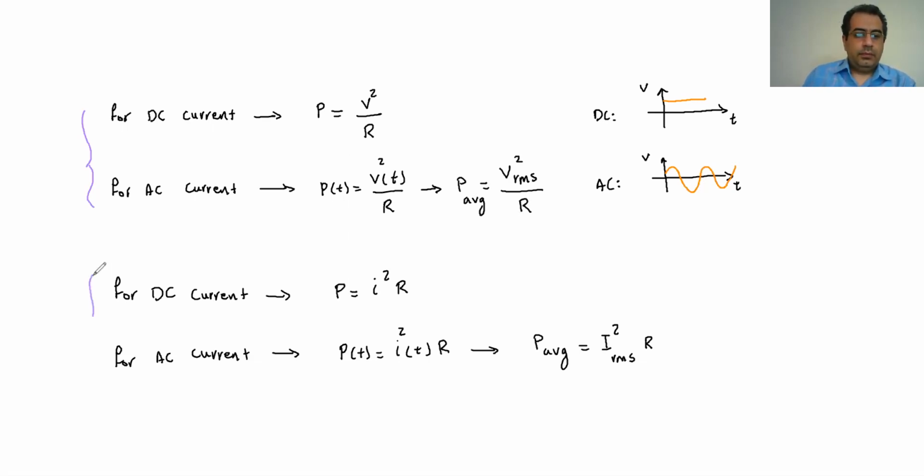So in other words, anytime we have the equation in DC current that we had before and we use it to calculate something, if we want to find those values for the AC current, use the RMS value instead of the variable you have in your equation. If you use the RMS value, what you get is the average of that.